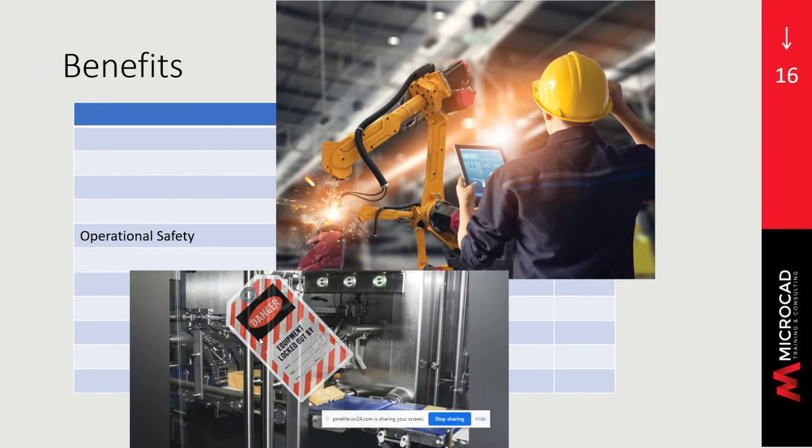Before a maintenance project is begun, the project manager can identify all of the risks from the model and plan accordingly. Any lockouts can be identified and planned for. Lifts can be planned ahead because the digital twin has the equipment weights and center of gravity.